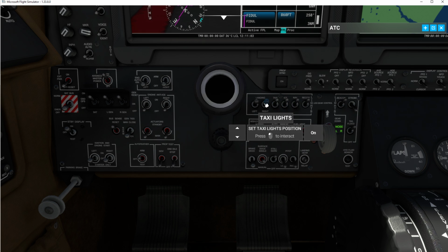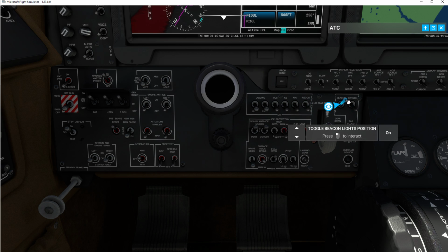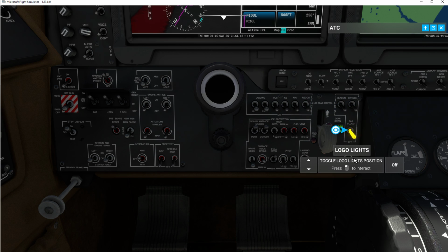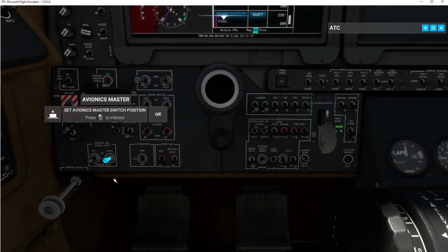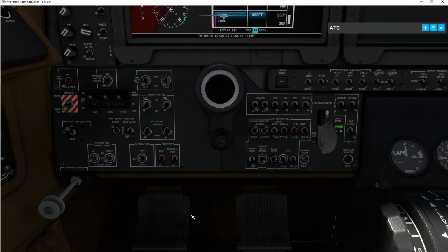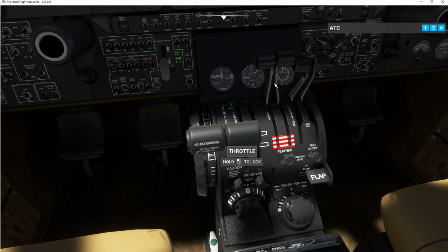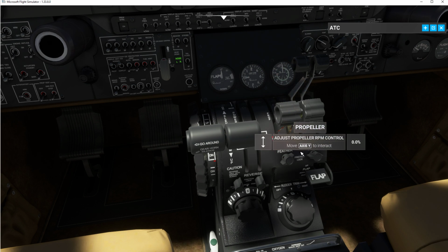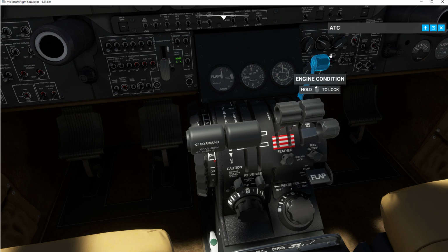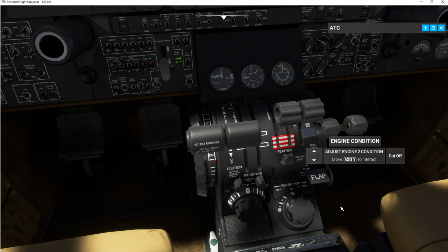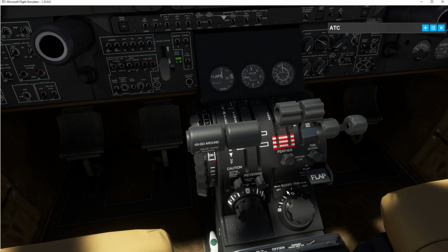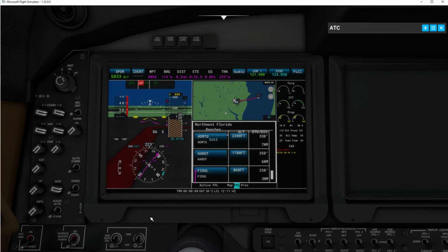And these lights can all be turned off. Okay. The P-TOTs are off. Avionics we can turn off. Okay, so that has to be on idle. These down, these fuel cutoff. That'll stop your engines. Make sure your flaps are up. And let's see what else we got here.